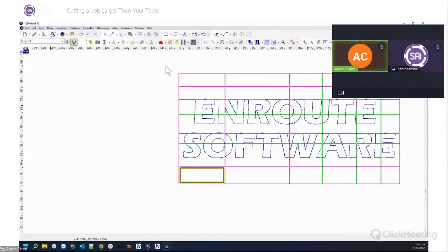Even with rapid texture, you might run into an issue if you got way too big. Let's say you're going to do a massive wall. I would probably just create a symmetric texture and then just repeat it a bunch of times. Especially if I was using rapid texture, or building a wall with a 3D texture, I would just create the 3D texture. And let's just say I was using 4x8 panels. I would just create it in the 4x8 and then make sure that it was a repeatable pattern.